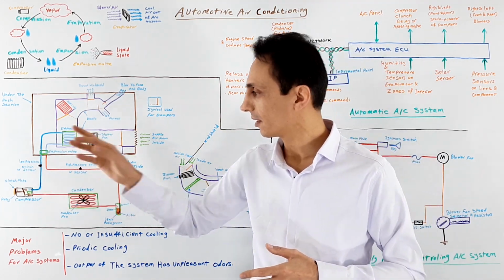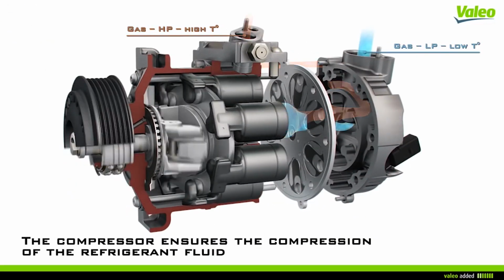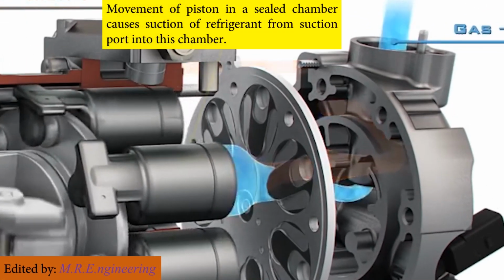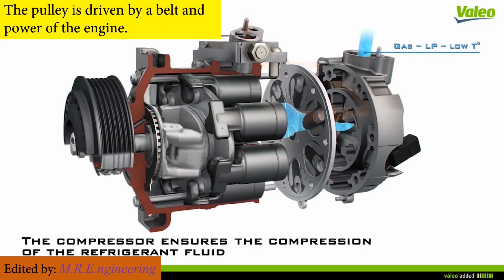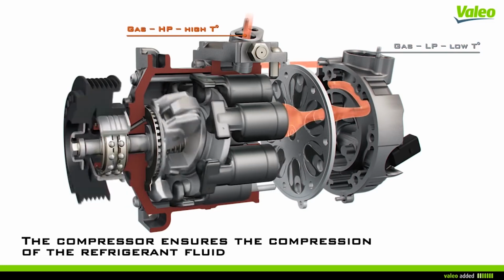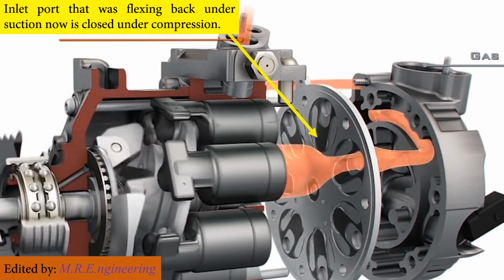I start again with compressor. When the compressor comes on, it sucks refrigerant into a low pressure chamber. This low pressure chamber is formed by the movement of a piston or plate that is moving by rotation of a shaft that it turns by the torque that is applied by the engine power through a belt, or for electric or some hybrid cars by an electric brushless motor. When the shaft of compressor rotates, the piston or plate that caused the suction now tries to compress the refrigerant, and on the compression the inlet valve closes by a check valve. But the output valve can be opened at a pre-adjusted pressure.